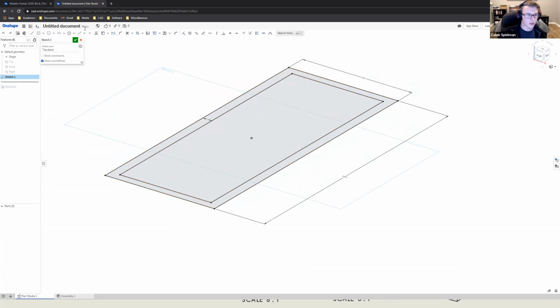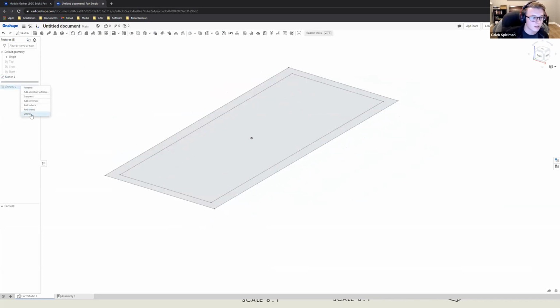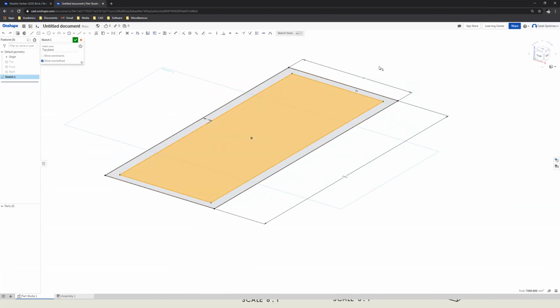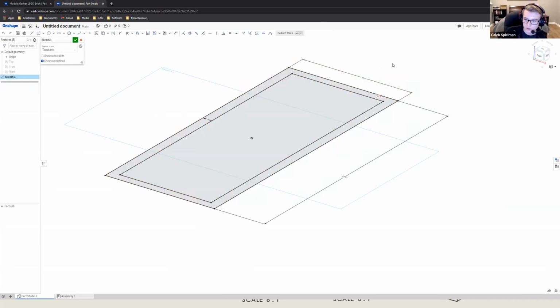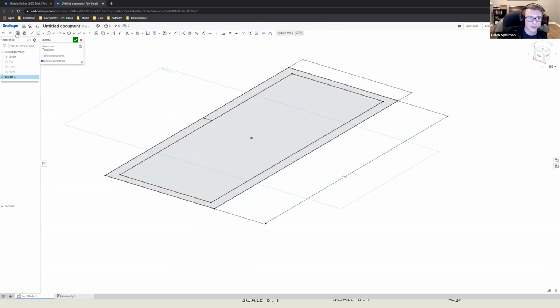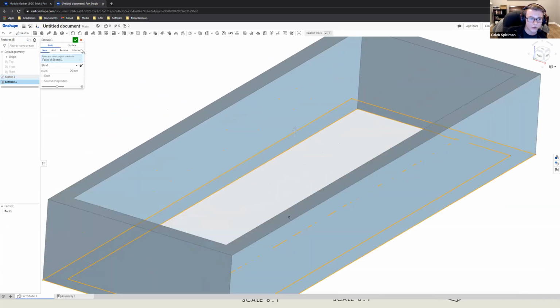Yes, I'll actually show you how to do that right now. So here, if we edit the sketch, we have different contours. There, if I click on a contour, there you go. How are you selecting those? I go over the shaded region and then I just left click. Oh, yes. Let me try that. So now I can click the extrude feature in the top left. Jackpot. The two boxes. All right, that's good.